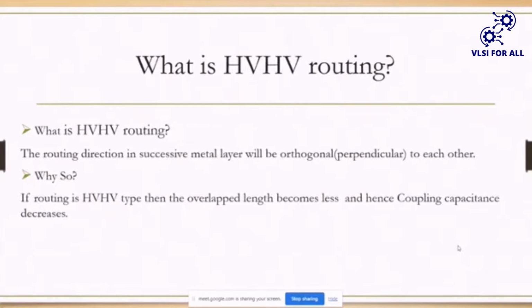No. Whatever pins are present in M1, from that M1 pin we go upward to M2, M3, M4, M5, and again come downward M4, M3, M2, M1, and we connect the pin. So this is all routing. In a single word, if you ask me what is meant by routing, it is connections only. How you connect between 2 points. Remember team, one more time, it is routing.